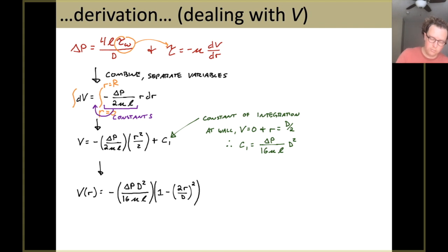Right? And so this is not describing the average velocity in the pipe. This is saying when you're at some radius. And so let me draw this just to be really explicit about it. So here's our pipe in black, and there's the center line. The distance r is how far away you are from the center line, and how fast the fluid is moving at that point is this V_r. So what you've just done is describe the velocity somewhere within the pipe.